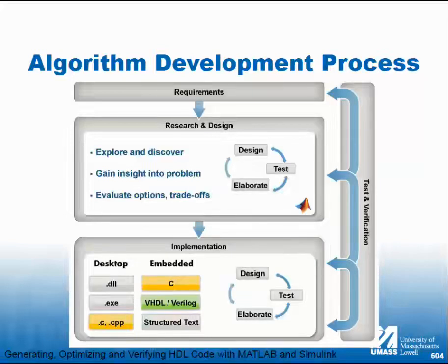Here's the problem when it comes down to digital design. In digital design, we work with gates and flip-flops. Gates and flip-flops are logic elements and state elements. State elements need clock and reset. This tool doesn't understand clock and reset unless you impose it on the tool. So even when you write a state machine in Simulink, it just changes state when the proper event happens on the inputs. So you have to make it a clocked state machine.